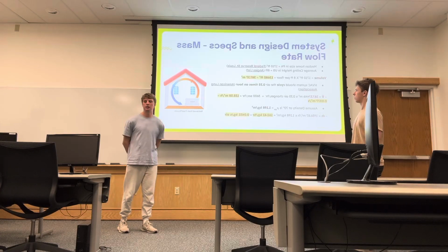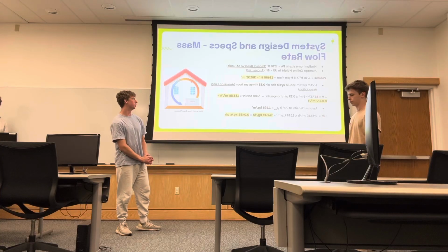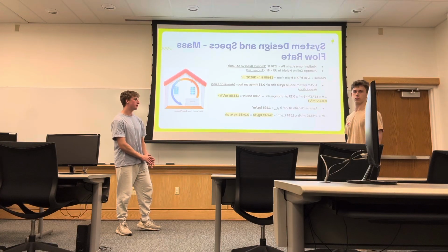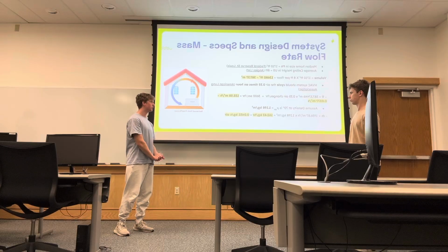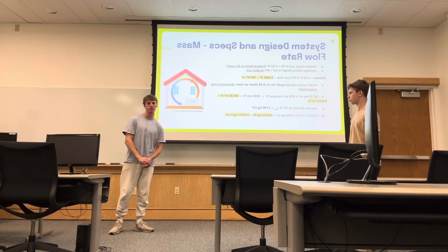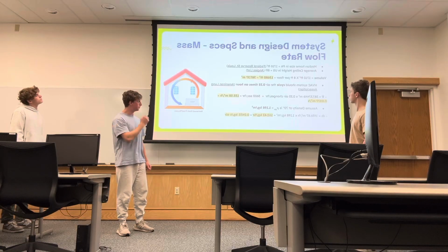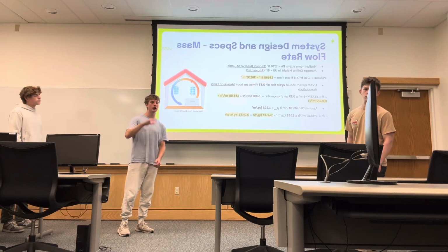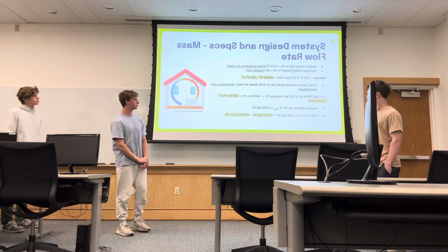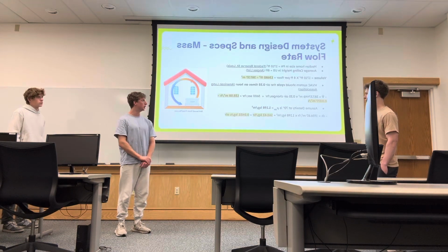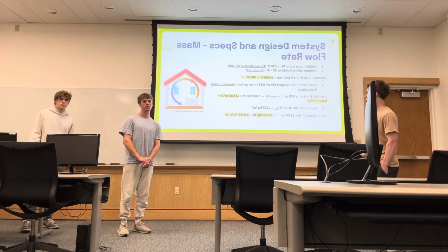After we got our conceptual design, we first started working on our calculations. We first found the volumetric flow rate and mass flow rate by taking a few assumptions. First, we found the median home size in Pennsylvania, according to the Federal Reserve, to be about 1,700 square feet, and the average height of ceilings in an American residential home to be 8 feet. Doing simple calculations, we found the volume of the house to be 13,000 cubic feet, or just under 400 cubic meters.